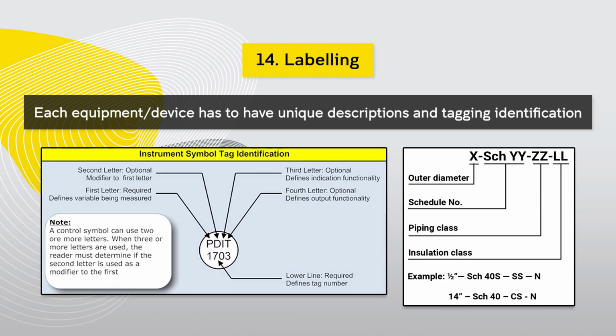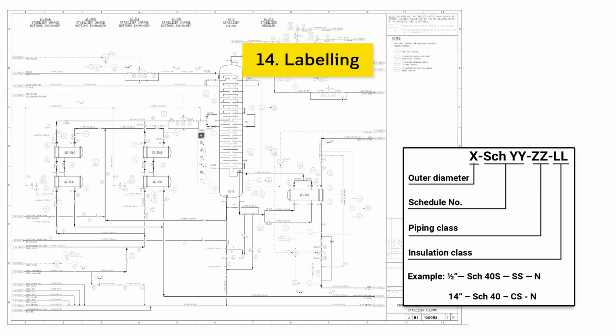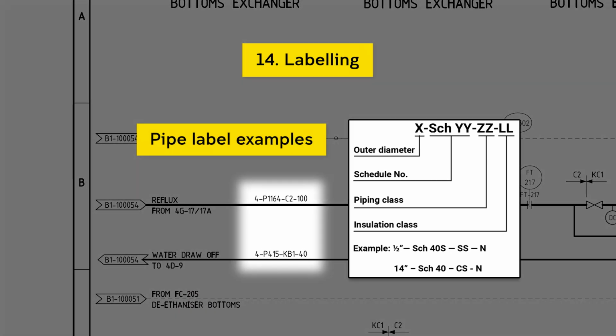It's important that our pipes all have a label on them. And generally what people want to know is the diameter of the pipe as a minimum. Usually they'll want to see what material that pipeline is made of. There are some additional things you can put in there. Example of fluid code. What kind of fluid is it that's running through that pipe? That's kind of nice to have, not mandatory, but certainly you want to see the diameter or the size of the pipe. You want to see the material. They're pretty key things. In every pipeline, you should be able to work that out.